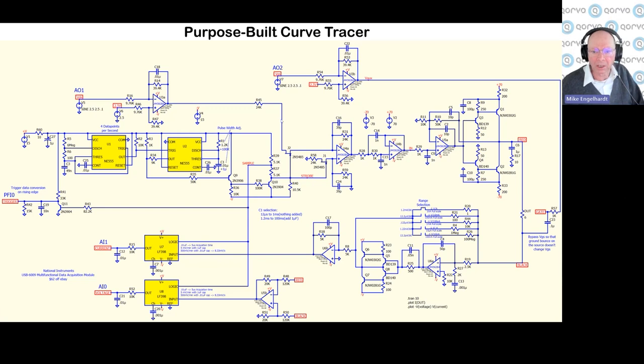So I have to take a DC level and pulse it. This is a fairly standard technique of using a JFET to chop a signal. But if you do this, you get some charge injection, so it doesn't look like a little square wave. It's a square wave with big jolts that can be bigger than the wave itself.